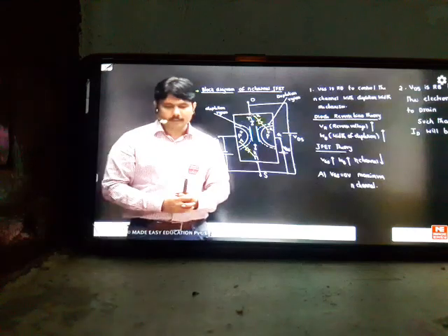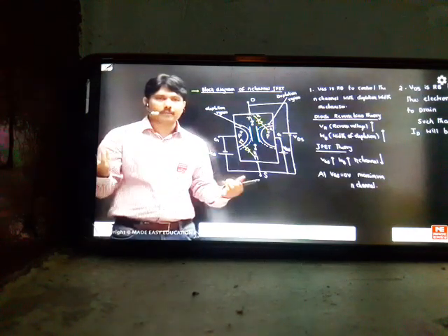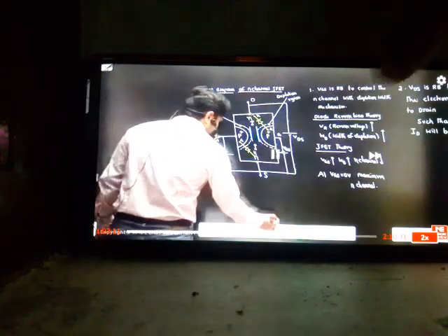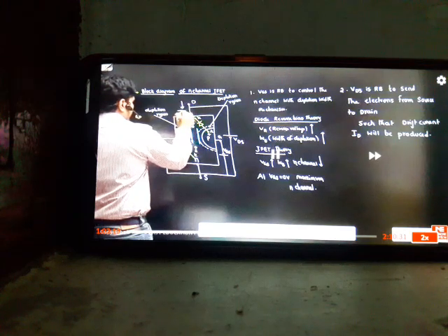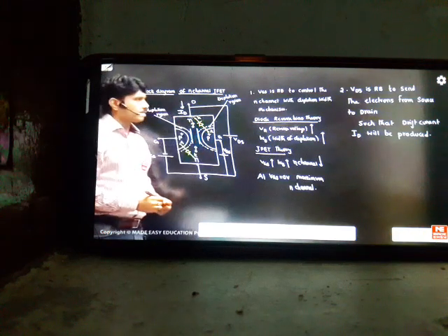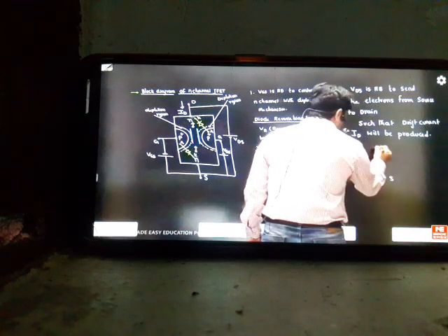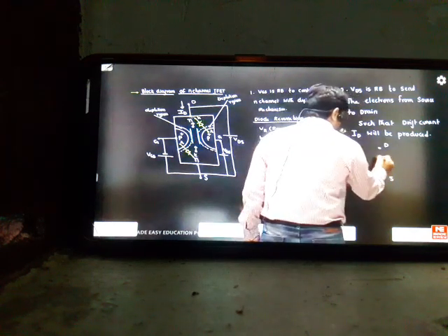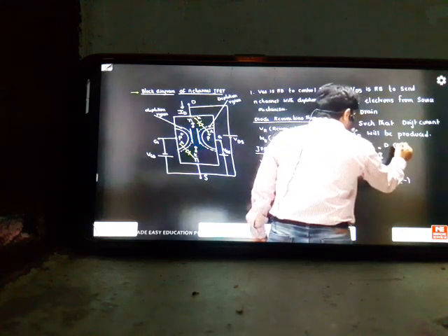That is the mechanism. Automatically the drain became reverse bias because it has to attract the electrons. Therefore, the N region we connect to positive, and the drain automatically becomes reverse bias to give the drift current ID. So you can get an ID current here. The ID current flow direction will be downward. As electrons are moving upward, the direction of the current will be downward. Electrons are moving from source to drain, like this in the channel. So the source I said to connect negative polarity, and the drain positive polarity like this.